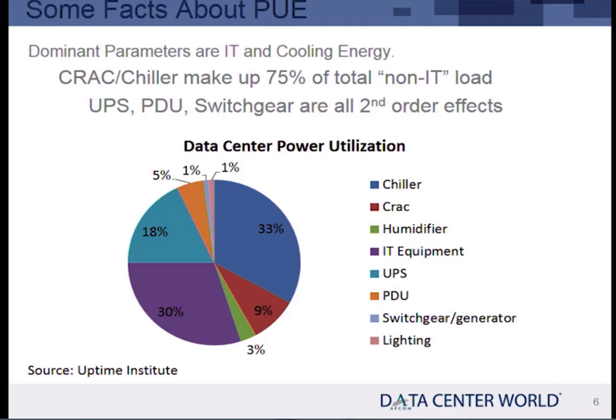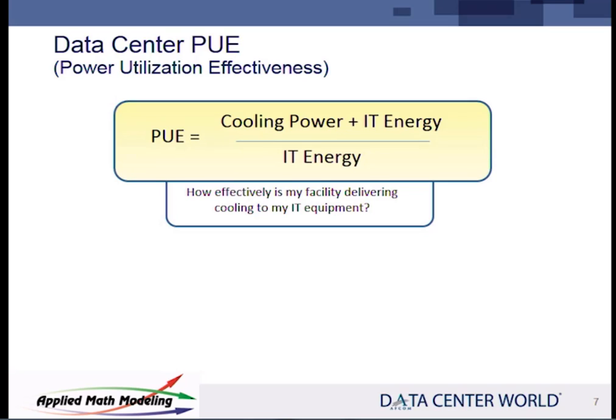But anyway, it's chiller power, fan power that dominates it. UPS leakage is getting much better. The UPSs are getting more improved. The PDUs are getting more improved. So you're still dominated by cooling in that numerator. So it's really cooling power is the dominant parameter. And whenever you're trying to optimize something, look for the dominant parameters. What are they? Cooling power. It's the elephant in the room.